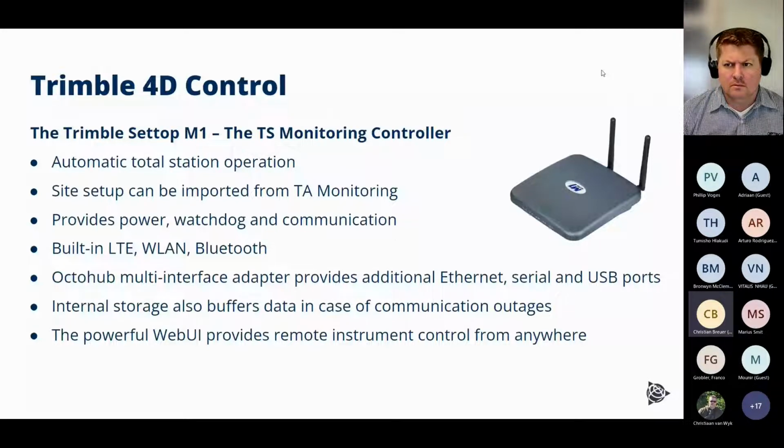You just need one cable, yeah, from the controller here to the total station, and one power cord from mains into the controller. So the controller itself will power the instruments. You don't need any batteries in the instrument. Yeah, it has a lot of functionality like watchdog, all the communication you need. So you put a SIM card inside, yeah, and simply connect it to T4D, and it will automatically do the observations for you according to the schedule.